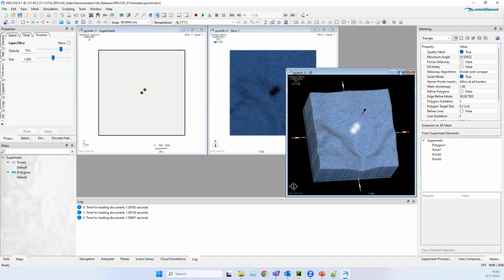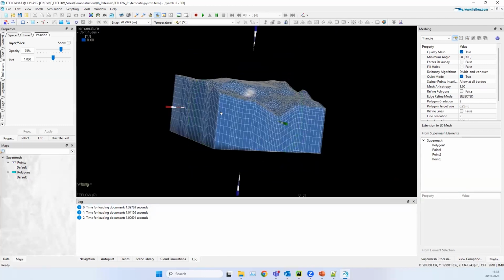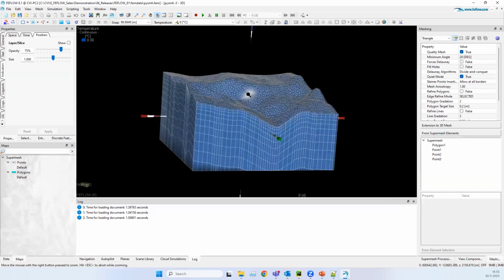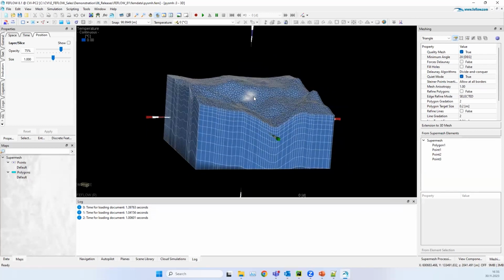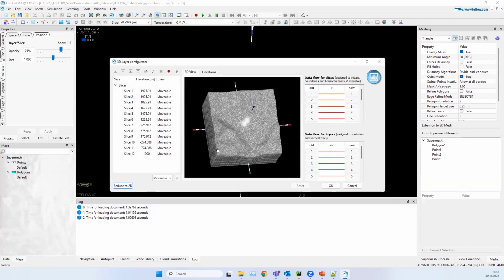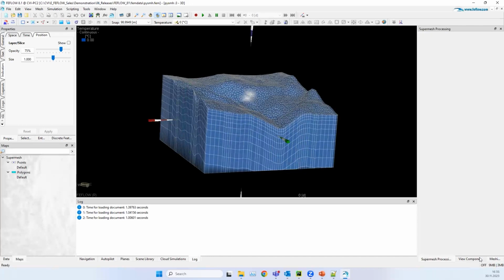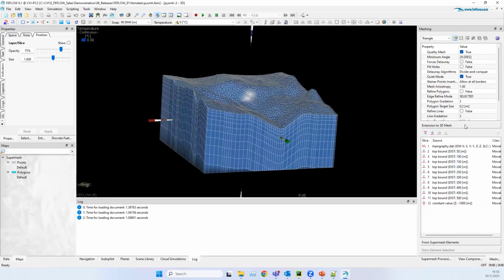For complex models, it's obviously applicable, so you will need to define the elevations in the different slices, and the interpolator will do the job. What it's basically doing is following the same concepts that we have in the layer configurator. So we are calling the layer configurator from Python, and the extraction of the 3D model that you have seen is exactly the same extraction that we will have here in this extension to 3D. It's exactly the same.